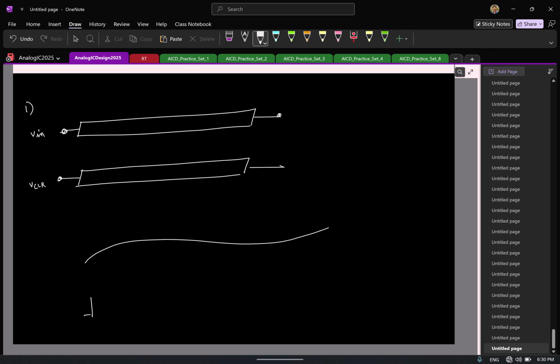And you have a clock like this going from 0 to VDD. What I'm saying is this amplitude might be a couple of millivolts, whereas the clock amplitude can be about 100 times that. Now anytime you have two metals running in parallel, what forms? A capacitor forms. Remember that anytime you have these jumps, this corresponds to low frequency or high frequency? High frequency. At high frequencies, what can you say about the capacitor? If it is going to be a short at these transitions, what will happen now to the signal?